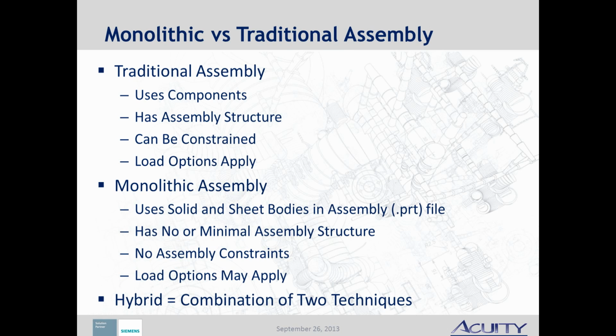The other thing about traditional assemblies that's kind of a downside is that more management is required. You might find yourself setting up load paths, or if you've got lots of files in lots of places on the network, and you need revision control, you may need the data manager to help you with that, because the work organizing traditional assemblies may well exceed the value they bring to your workflow.